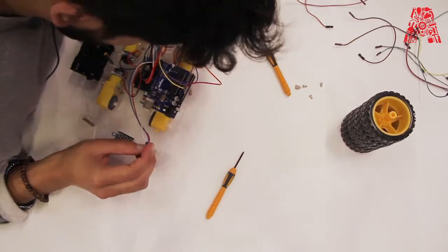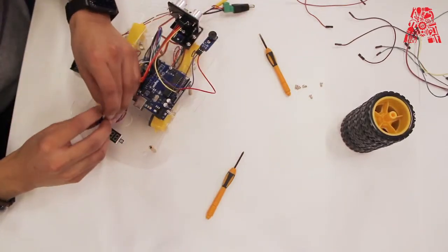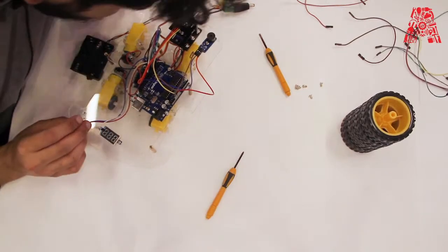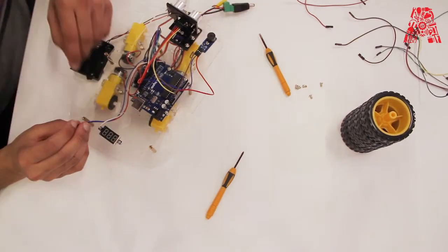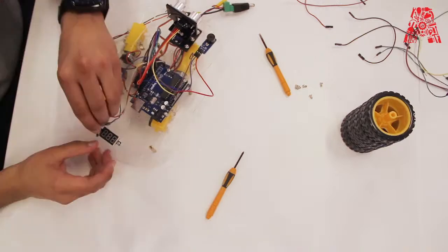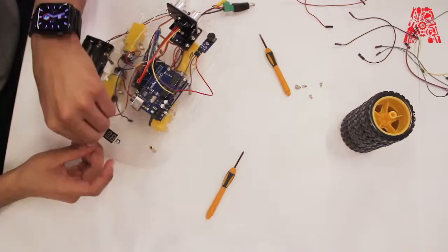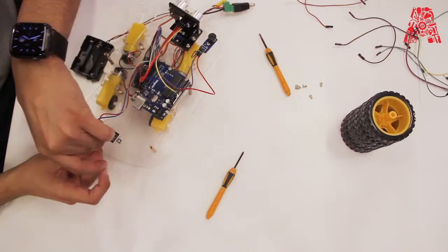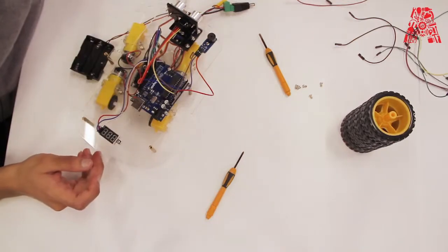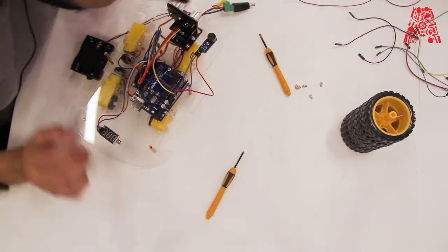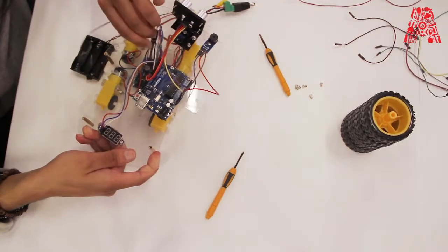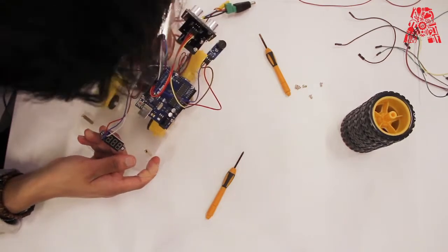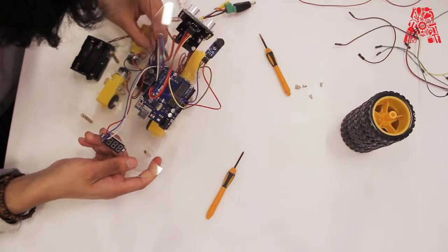Okay, so the 0 volt is connected to the white one, so the white one will go to VT. Then 12 volt VCC is connected to the red wire, so it's going to go to VCC. And then the blue one is the ground, so it will go to ground. And then there is one more wire that needs to be connected, which is the signal from here, and it will be connected to the signal pin of the motor driver.